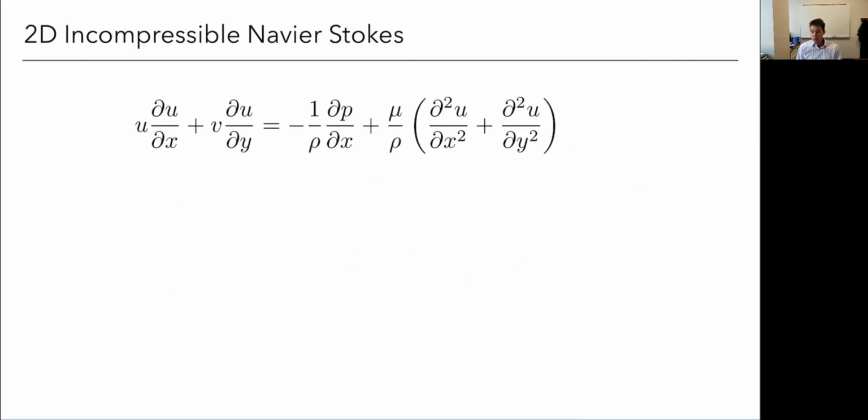This is not non-dimensional as described, right? There are certainly dimensions in here, but I could non-dimensionalize this. So let's do that. For example, just to start, I've got a velocity term here. So maybe I just want to divide everything by velocity, and a good characteristic velocity would be my free stream velocity. If I divide my whole equation by the same thing, I didn't change anything, right? So I'm going to put a V infinity here in the denominator, and I'll put a V infinity here.